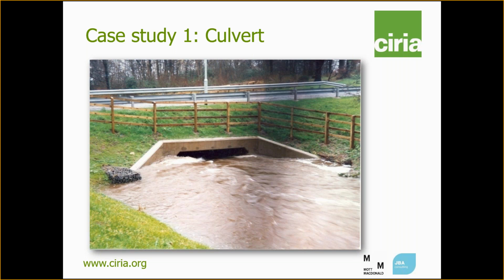So if this culvert did block, or if the design flood was exceeded, flow would flow over the road in extremis. And in this particular location, that's important because if the road was higher and didn't provide the overflow, the first place to flood would be a large housing estate, industrial estate immediately upstream.